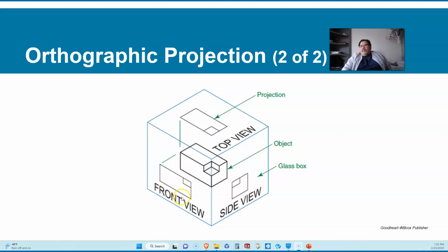And that might be the front, the side, and the top, or the front, the side, and the bottom. You might see the top, the bottom, and one side, or the top, the bottom, and the other side, but you'll never see more than 3 in any particular view.